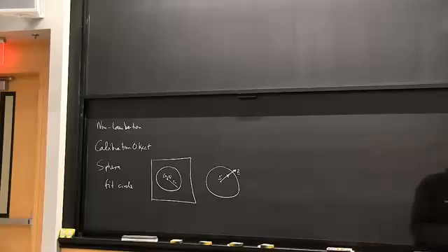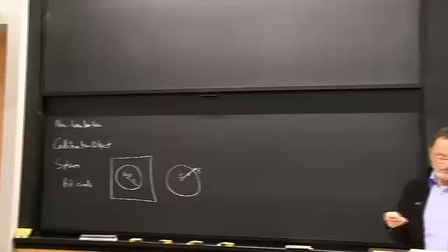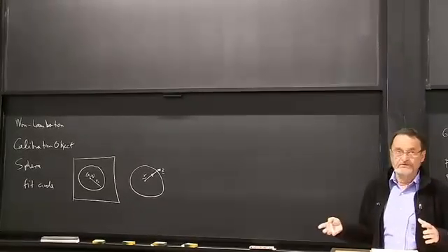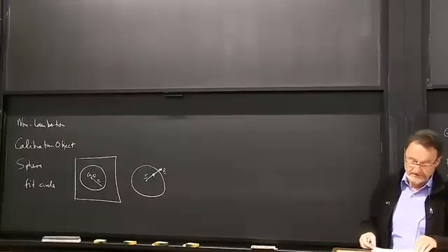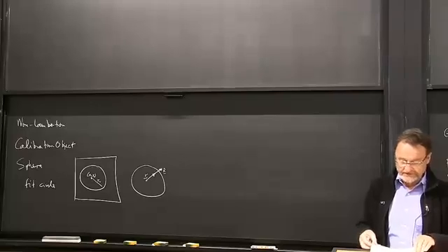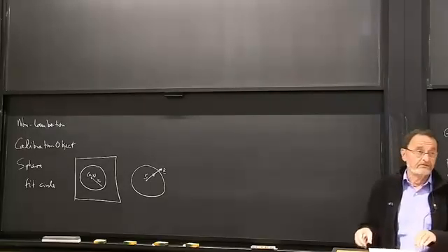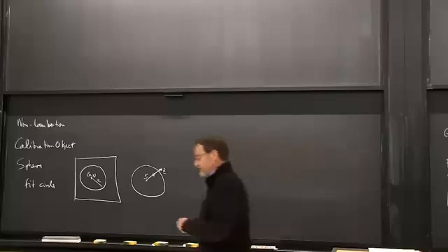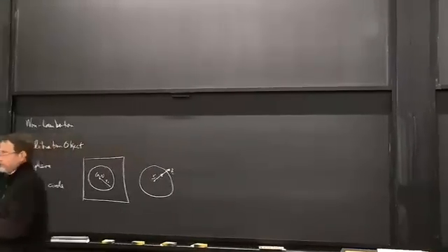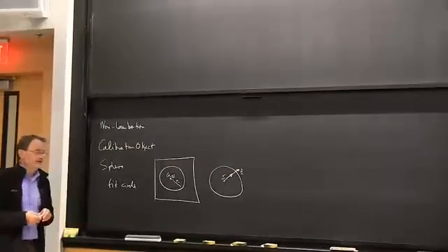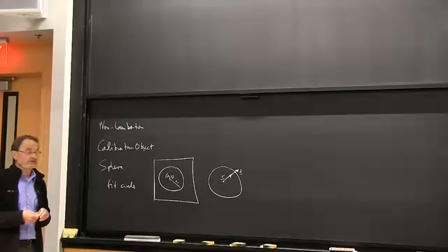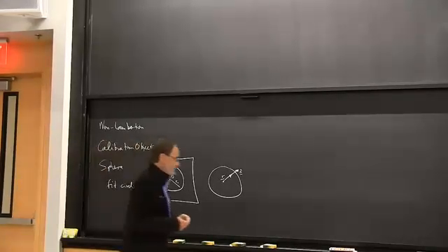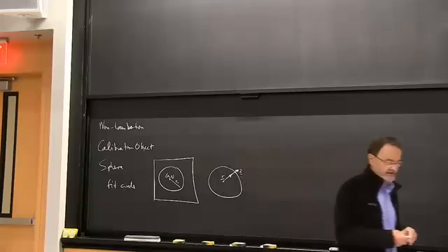So it makes it really easy to know what the surface orientation is, because we just connect the center of the sphere to the point on the surface you're interested in, and there's your orientation. And of course this doesn't quite apply to the Earth because it's not a sphere, so we need to modify that slightly. And that's why there's several different definitions of latitude, depending on whether you're talking about the local surface normal or the vector from the center of the Earth. And usually we take the local surface normal as the definition for the angle that's latitude.